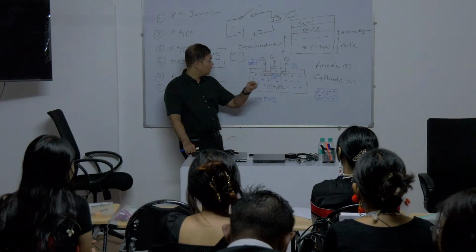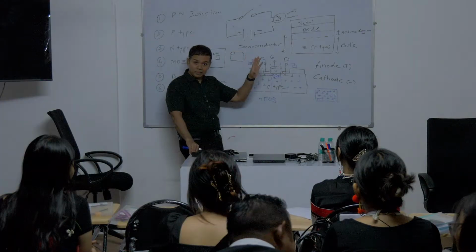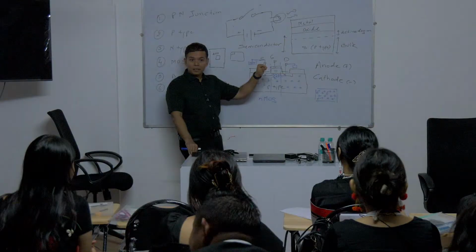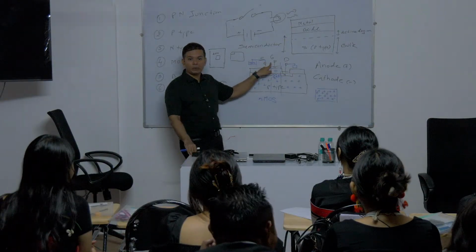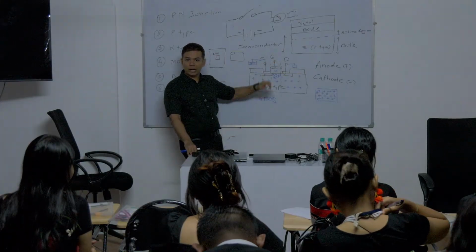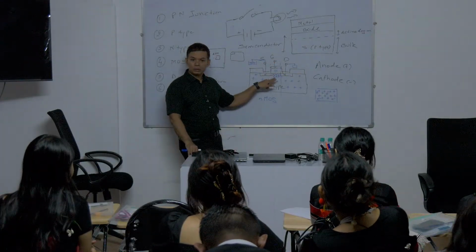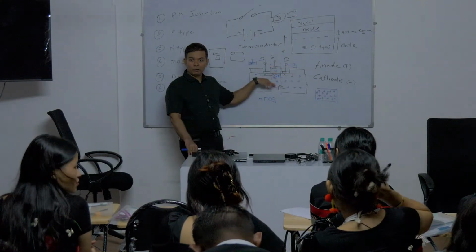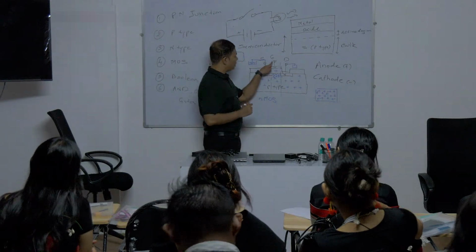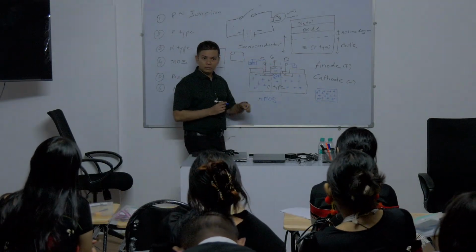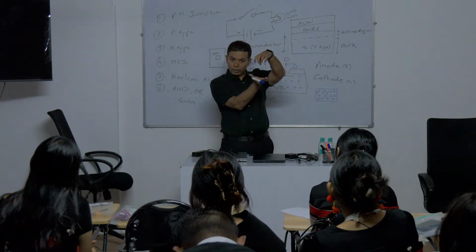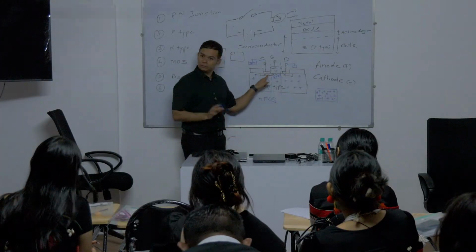So now, after creating a channel, the device is on. Once it is on, you will keep that voltage as it is, because you still want the channel to be there. As soon as you remove the voltage from here, what will happen? Tell me, if I remove the positive voltage, will the electrons remain over here, or will they fall back? Just understand this. When I'm giving a positive voltage at this end, the electrons remain at this location.